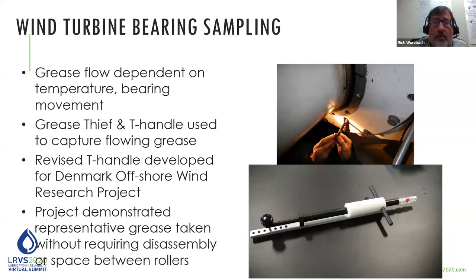And this project was really helpful because not only could we take that sample and analyze it, that was already scheduled. Some of these bearings were already scheduled to be taken down and overhauled. So there was the opportunity to tear them apart, to look inside and see what the real condition of the grease and the bearing was. And in each case, it matched up to what we were seeing in the grease samples.